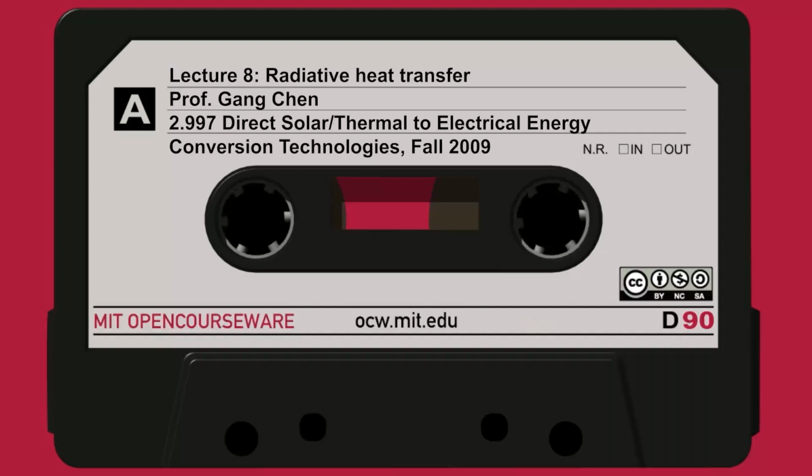Now you use a more realistic absorber. The blackbody is just the overall spectrum. Let's say here is a selective absorber, so you get a higher efficiency, and if you compare these two, you can also operate at a higher temperature. If your selectivity is good, you can push to a higher temperature. If your spectrum is not good, as with a blackbody, you don't want to operate at high temperature. You want to operate at low temperature because you're losing too much heat.